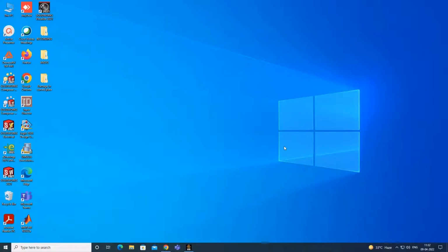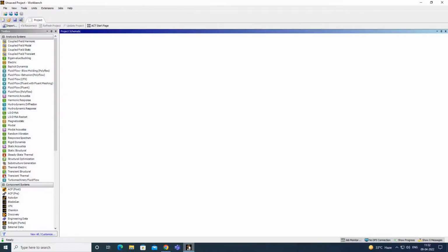In this video, we are going to perform the static and thermal analysis of composite plate. So we will open the ANSYS Workbench. First of all, we will model the composite plate using ACP-Pre. Then we will do the steady state thermal analysis followed by static structural analysis.